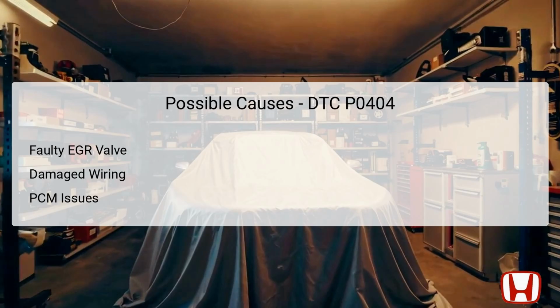Each of these causes can create a situation where the command and actual position of the EGR valve do not match, prompting the PCM to trigger the DTC. Identifying the root cause is vital for ensuring that the emission system operates efficiently and complies with regulatory standards.